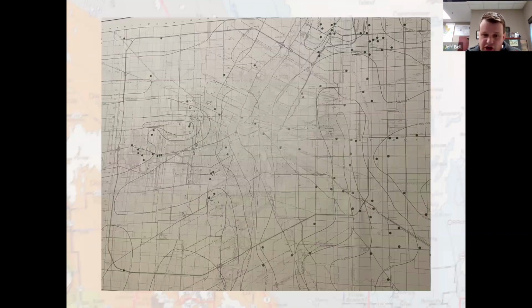This is a shot of a map series that was produced in the early 1980s by some authors that were doing some work at the University of Manitoba. The transmissive conditions, even across Winnipeg, changed dramatically. You can see in the downtown core here, we have what we consider to be a fairly low number of 10,000 US gallons per day per foot. But then when we extend out towards the airport, we see that number has grown to almost 250,000. So the conditions across Winnipeg can change in a very short distance.